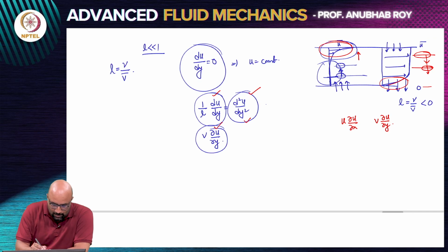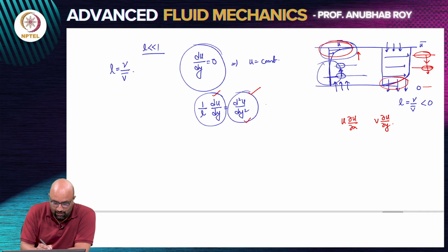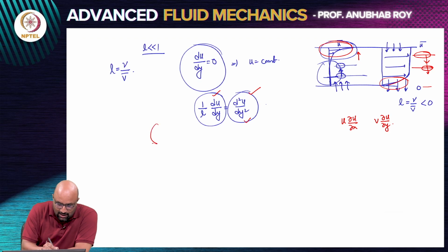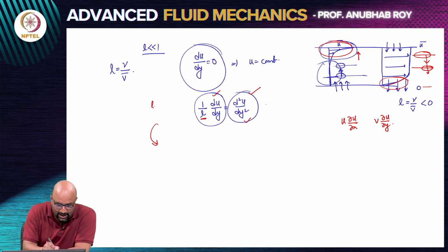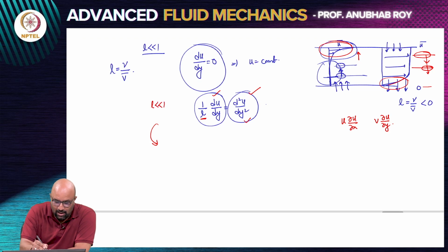So the primary reason I am doing this right now, in a part on laminar flow, is that you can start thinking that this fact, that there is a certain region over which viscous diffusion and advection compete, appeared naturally. If you see there is this L, and I am saying that when L is very small, I should be able to drop this, and we arrived at a contradiction where dropping it doesn't give us a solution uniformly valid over the entire region.